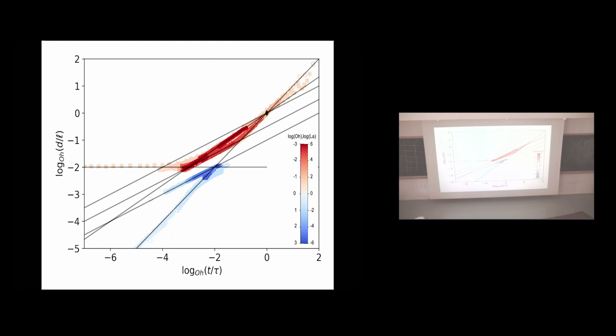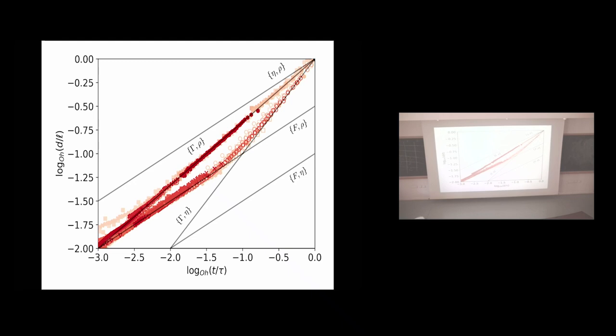Now it's really hard to read because all of those lines, all of those points are on top of one another. But if you zoom in, you see, for instance, in the case where you have mostly inertial fluids, so low Ohnesorge numbers, that some experiments go on one of the paths. The Ohnesorge point is here. You can have either the case of going 1/2, following Rayleigh's regime, and then meeting the other sets of data which follow the 2/3 regime.